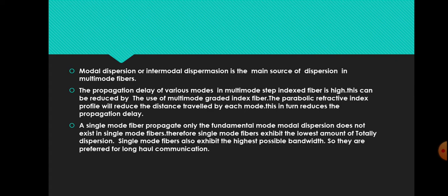A single mode fiber propagates only the fundamental mode, and modal dispersion does not exist in single mode fibers. You can see that intermodal dispersion results from the difference in the velocity of different modes when propagating through the fiber, but in the case of single mode there is only one mode, so there will be no intermodal dispersion.